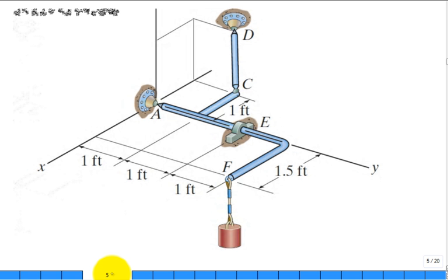And what do we mean by cutting it? In 2D, I draw an encircling line, but in 3D, it's really a surface. It's not a round surface. It doesn't have to have a particular shape, but it has to cut it. I'm trying to draw now a surface that's going to completely enclose my object, my body. That's the focus of the study. So, cutting through air, air doesn't exert a force or a torque or anything on my object.